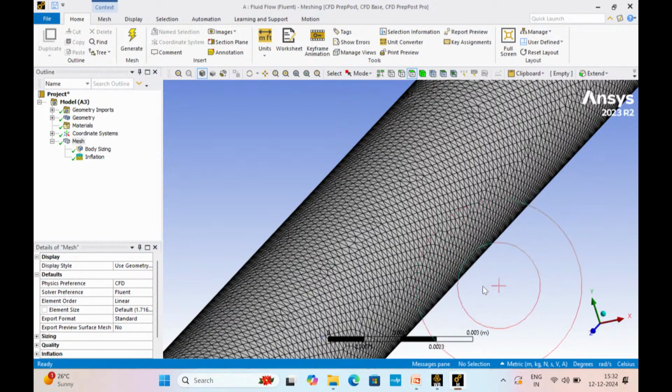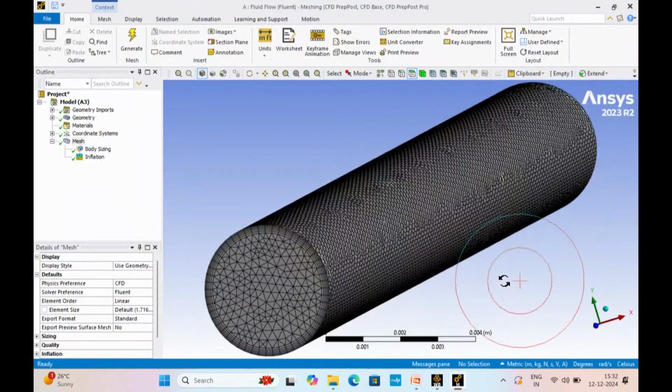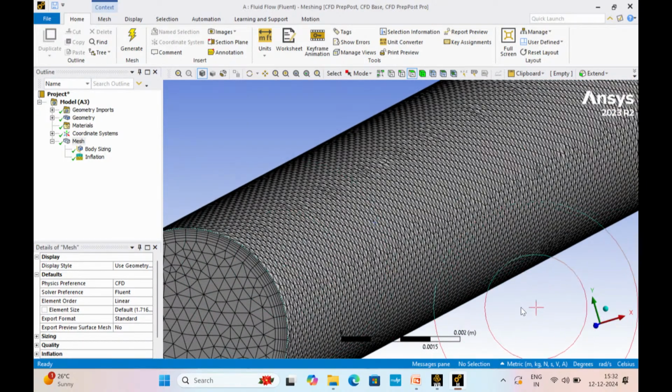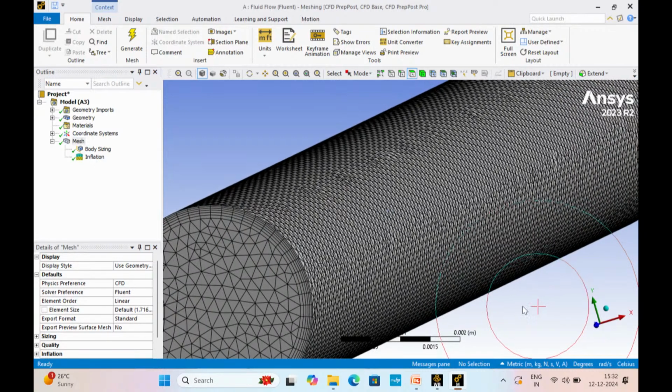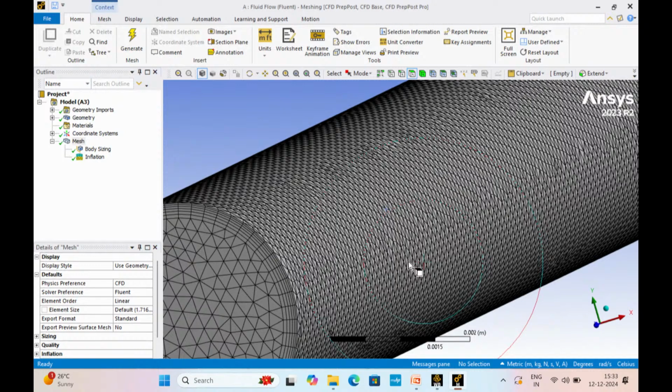So that is the problem here. It is very hard to control which mesh you want. Okay. So that's why now you see the ANSYS Discovery. It's a very nice one. You can use that mesh if you really want to make it hexa mesh. Otherwise, it's very hard to control. Okay. So that's, you see, they automatically change it. When we apply the inflation, the hexa mesh changed to, I think, a hybrid, some triangular mesh or tetrahedral mesh or some hexa mesh. So yeah, if you really want to do that, use ICEM.